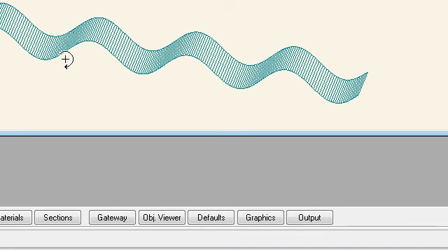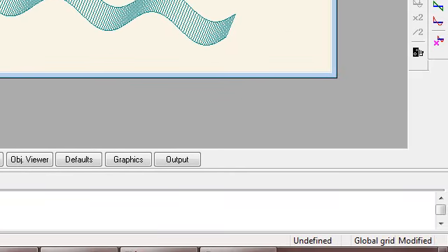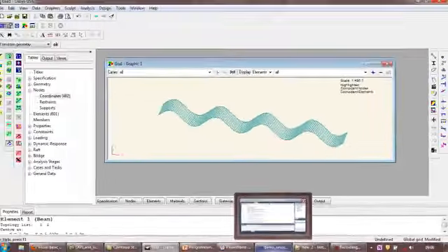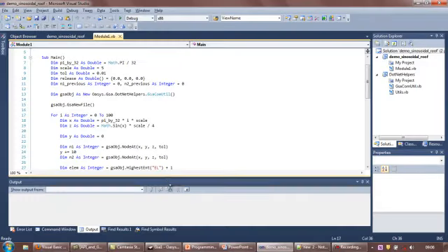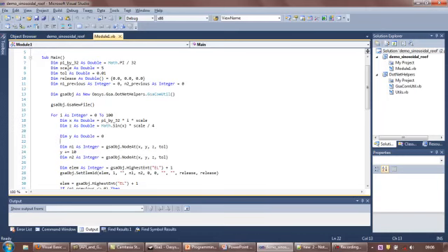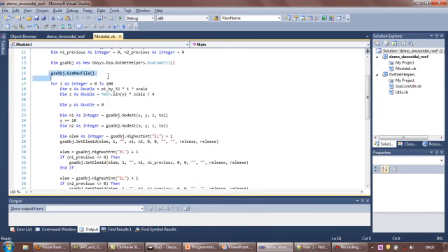And in real life the roof will not be as simple as that. But imagine if we had to do the same thing programmatically. We'd have to write a few lines of code like the one I have here. So open a new GSA model over here, and the XYZ coordinates are, the Z coordinate is the sine of the X coordinate times a scaling factor.